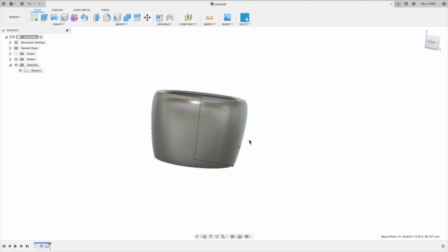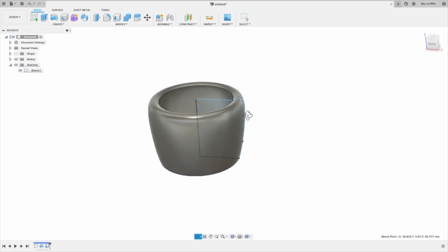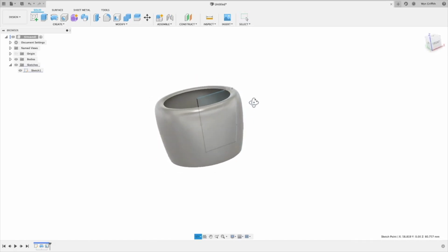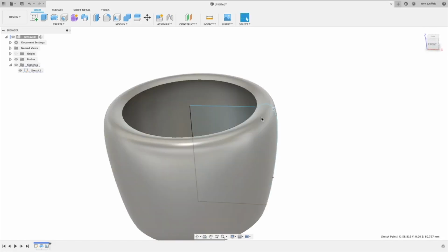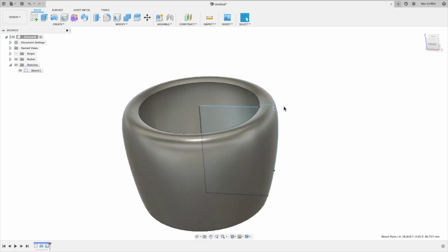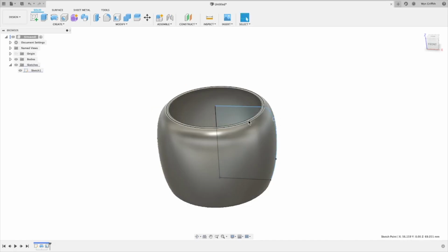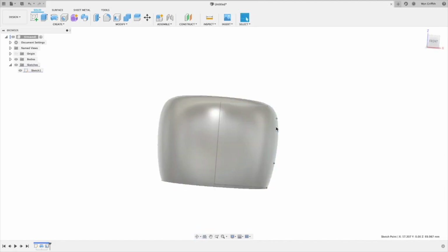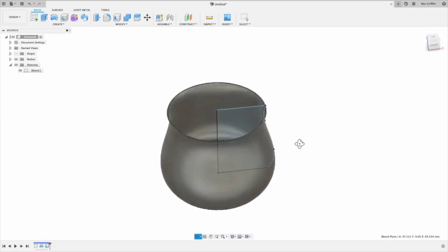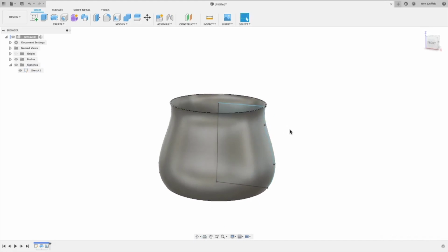So if you wanted to 3D print this, then you could play around with the shapes for 3D printers if you like. Something like that though is not very 3D printable because you'd need support material to hold up this rim while it's being printed. So you wouldn't really want to go over about 45 degrees, 60 maybe if you're lucky. But something like that, perfectly 3D printable.